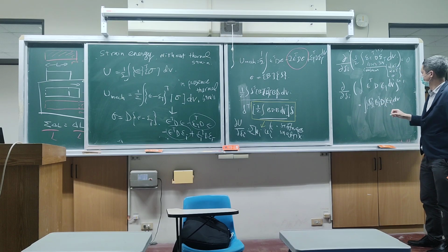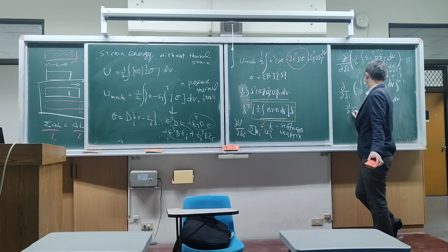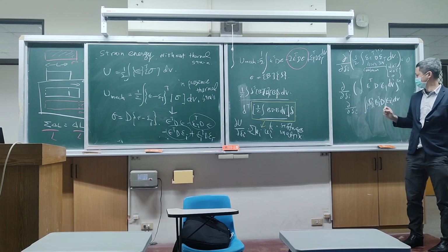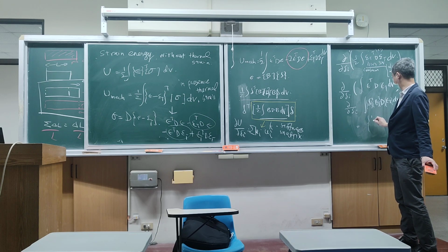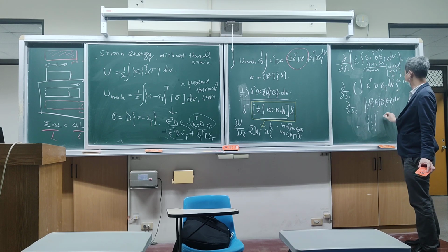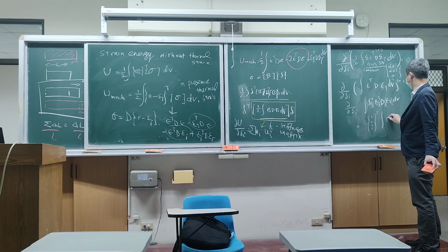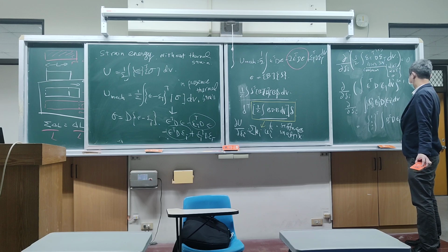Okay? So if you now try to differentiate it with respect to one of the displacements, okay, then this term is going to be 1, other terms all 0, okay, transpose, and your B transpose D epsilon T dV,